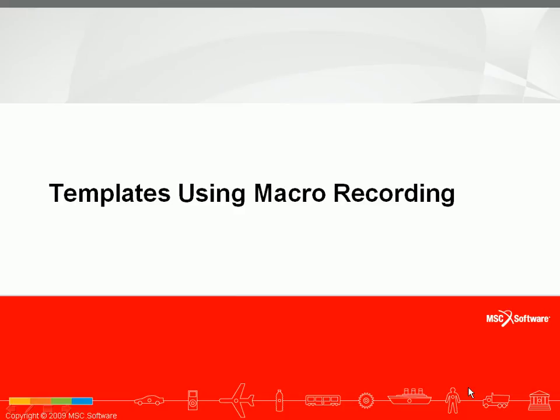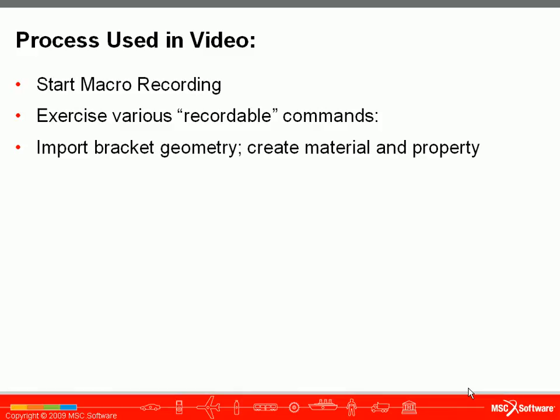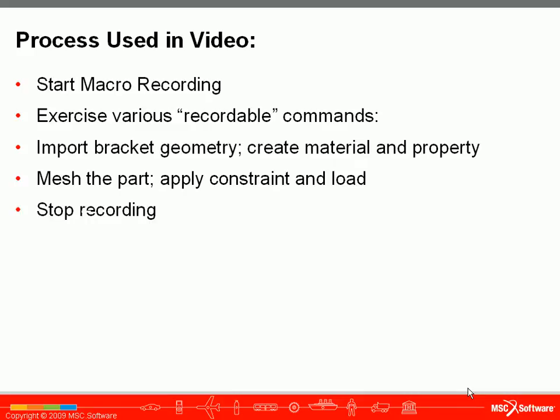In this video, we'll be using the macro record capability of SimXpert to create a simulation template. The procedure we're going to use in the video will be as follows. We'll start macro recording. We'll exercise various recordable commands in SimXpert, such as importing bracket geometry, creating material and property, meshing the part, applying constraint and load, and then we'll stop recording.